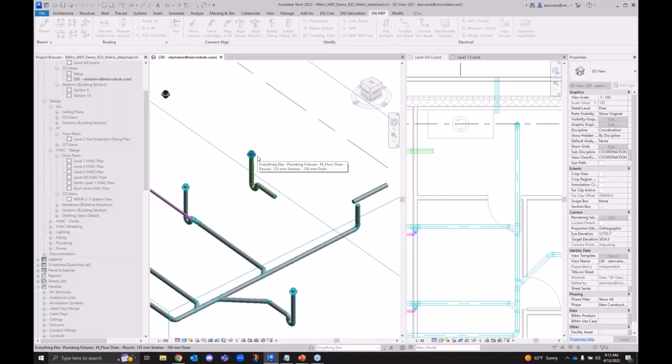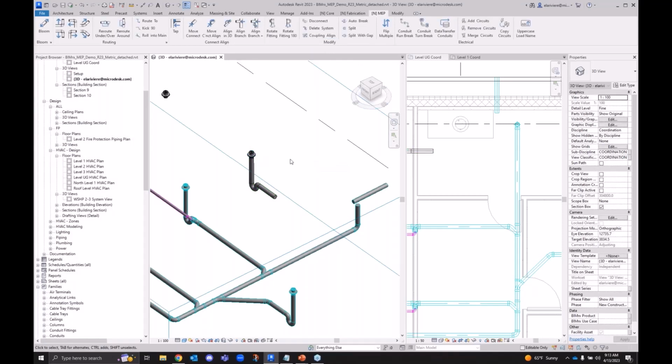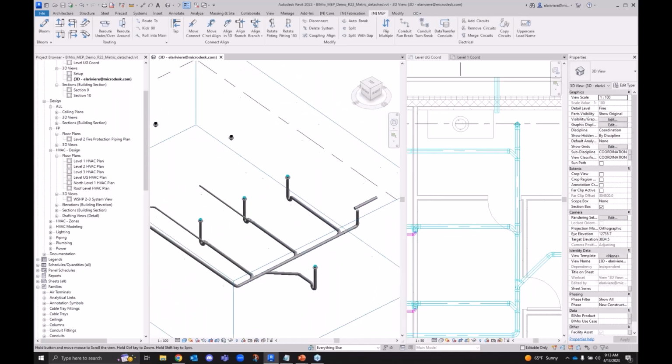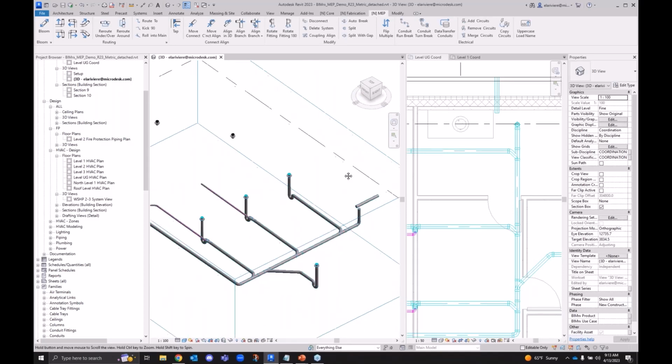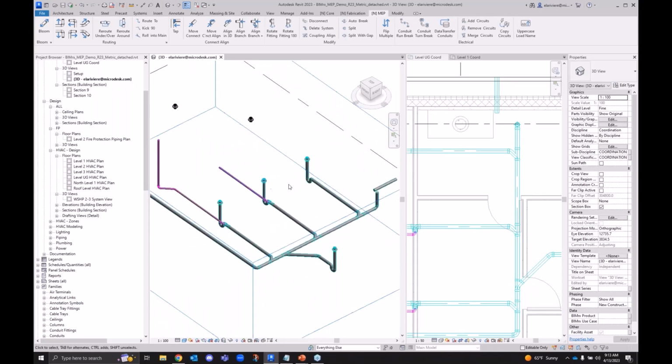So pulling the system out of the floor drain gets rid of the system all the way through, and we can go ahead and do that trim extend and inherit that drainage system through the rest of our system. So very, very quick to do that modeling, very, very quick to get it together. We're going to do just a little bit more down here underground, and then we're going to move into some above ground stuff instead. I do just want to show a little bit of this vent modeling and exactly how quick we can make that vent modeling go.